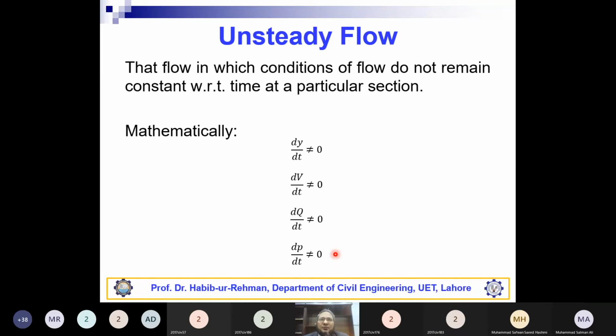Yes, it should be for pipe flow because fluid flows under pressure only in pressure conduits or pipes. In open channels, there is a free surface. And how much is pressure on the free surface? Atmospheric pressure. Or how much would its value be in terms of gauge pressure? 0. Yes, it would be 0.